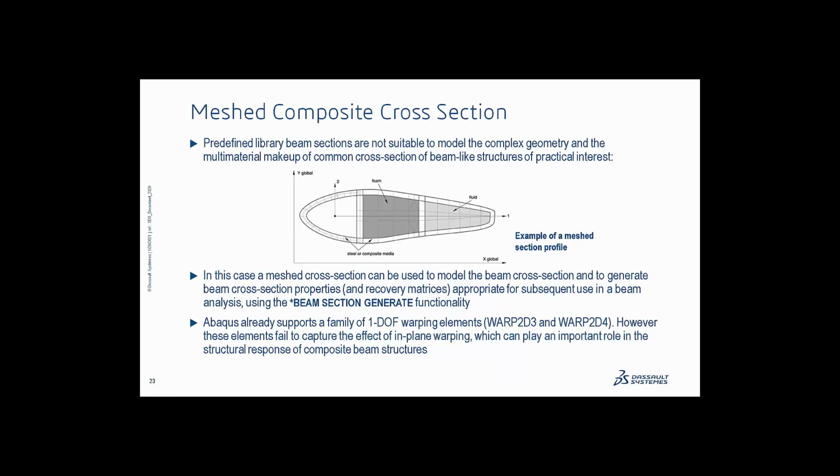If you imagine a cross section like this extruded out of your screen to a significant distance, there's a desire when you have components like this, especially with optimization algorithms, to abstract this into an equivalent beam property. And we can do that by meshing this 2D cross section, computing the equivalent beam properties, and then applying the resulting stiffness matrix to a beam using beam general section.